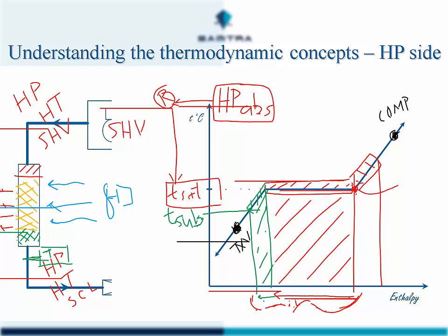So this first amount of heat being removed is a small amount of sensible heat transfer, and we can see that the total heat energy is greater. It's made up of the heat energy cooling down the vapors, the heat energy converting the vapors to a liquid, and then the heat energy cooling down the liquid. Right, let's move along.